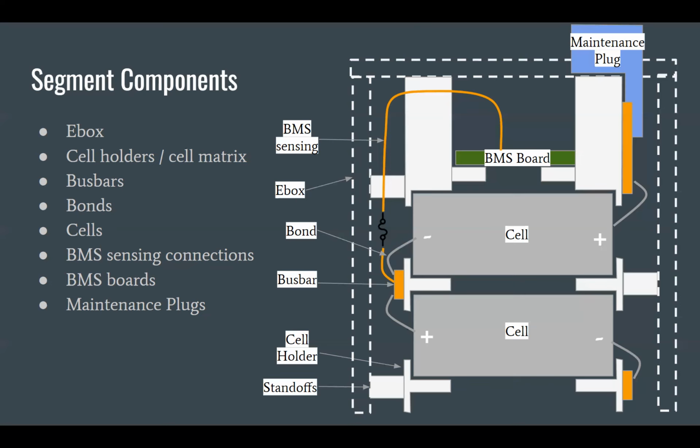management system sensing connections. Like I talked about last time, the battery management system has to actually detect the voltages and temperatures of all the cells in the battery pack, either directly or indirectly. For voltages, it detects all of them directly. And for temperatures, it measures the temperature near every cell, and we can use that to approximate what the whole pack's temperature is.